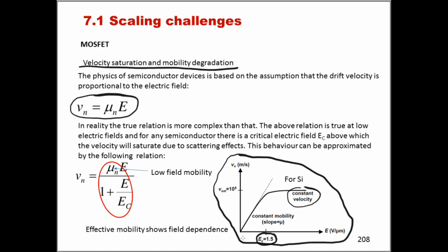Actually, as we've seen in chapter 1, for quite some time now, voltage has not been scaling almost at all. So the operating voltage of devices is not scaling, while we are scaling the feature size of the devices, which means that, in other words, the electric fields in the newly generated devices are actually going up.